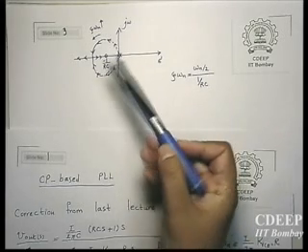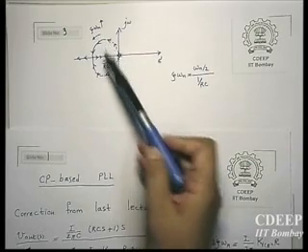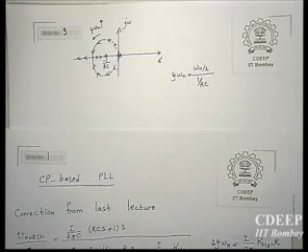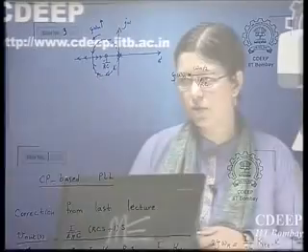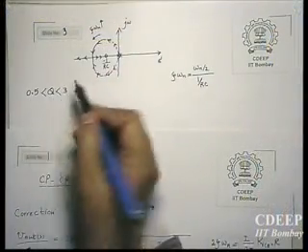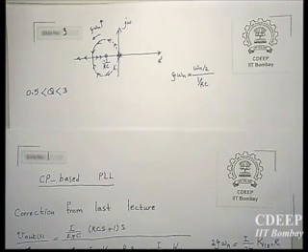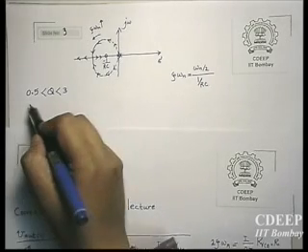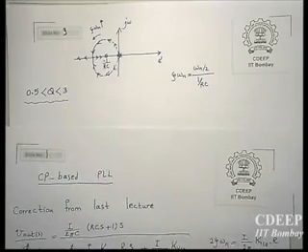On the other side, if you keep zeta omega n not very large, you will have imaginary poles and therefore you will get better settling, but then you should be careful about the stability. That's why usually in PLL the best practice for design is to keep the Q of this transfer function to be some value between 0.5 and 3. These are usually values which are used in PLL design. So your Q is not very high, not very low. This means that your zeta is not very high or very low. This is a very good practice for designing a PLL.